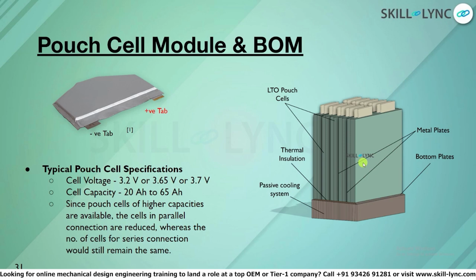And also what happens is, when you connect the cell to cell, the contact resistance by using a bus bar also has to be made sure that the welding is right, the welding is proper. So that is a challenge in cylindrical cells, because we have a lot of cells and you have a lot of bus bar to cell connections, and in such cases the welding has to be right, or else there could be a lot of contact resistance built up. And the same could be with pouch cells, but because the cells are less, you don't have much contact resistance added up because of less cells. So that is the advantage you have with pouch cell.